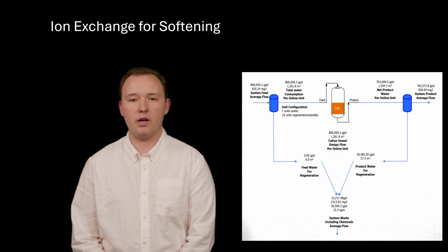When water comes into contact with a specialized resin housed within ion exchange tanks, it exchanges contaminants with more desirable ions on the surface of the resin. Over time, the resin's surface can become full, losing its purification abilities and requiring regeneration. This regeneration is done with a brine that takes back in the undesirable ions and resupplies the desired ones.